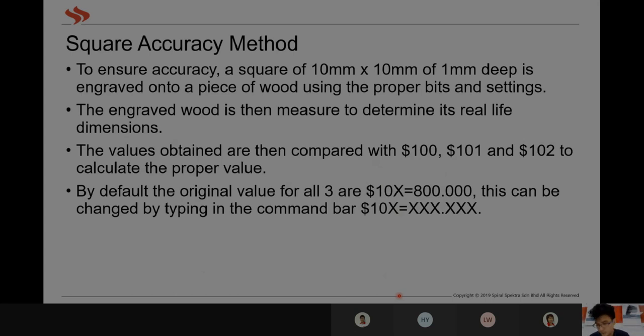However, you're not going to just do this once. You have to keep repeating it until it keeps giving you a consistent value. Because some values might be too much, some might be too low, so you're going to have to keep doing it until it's accurate. And over time, because parts are sure to wear out, you're going to have to keep doing this over and over after a period of time to keep your machine accurate.